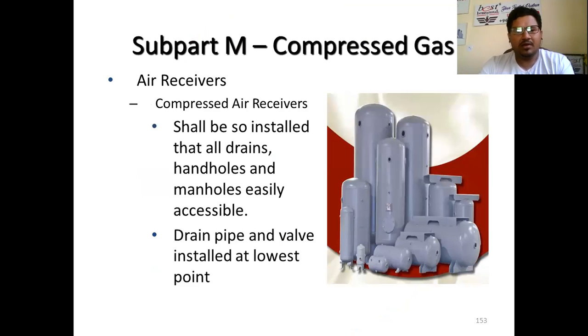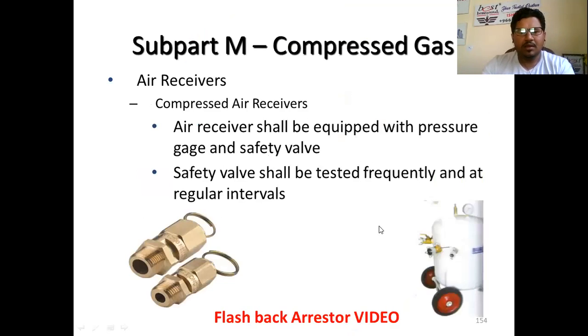So compressed air receivers shall be installed so that all drains, handholds, and manholes are easily accessible. Drain pipe and valve installed at the lowest point. And make sure the air receiver is equipped with a pressure gauge and safety valve. The safety valve shall be tested frequently and at regular intervals.